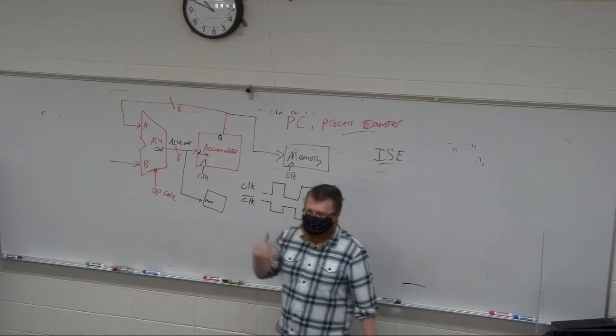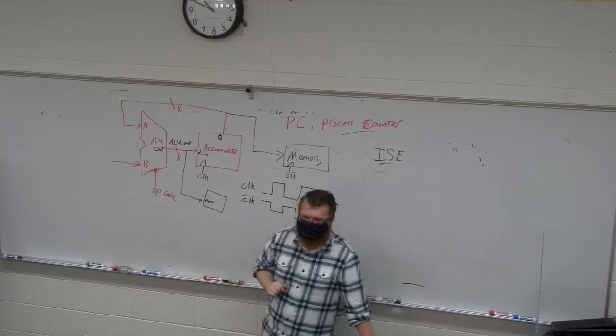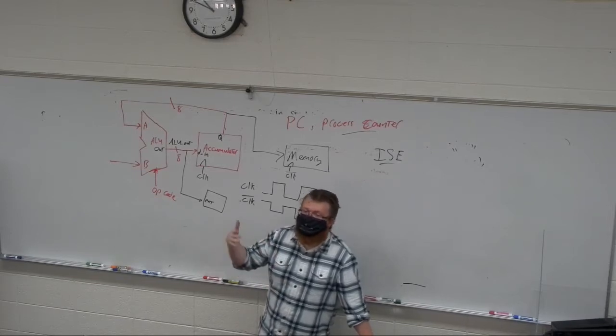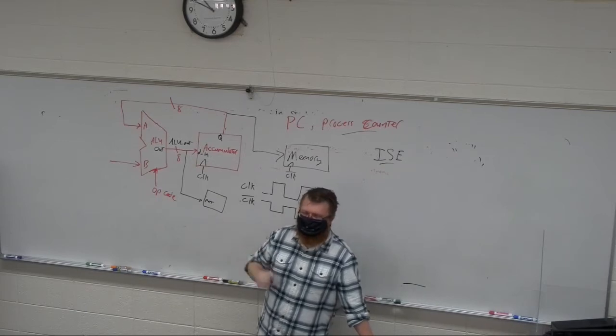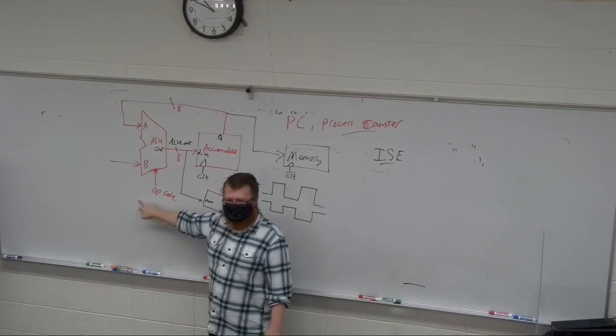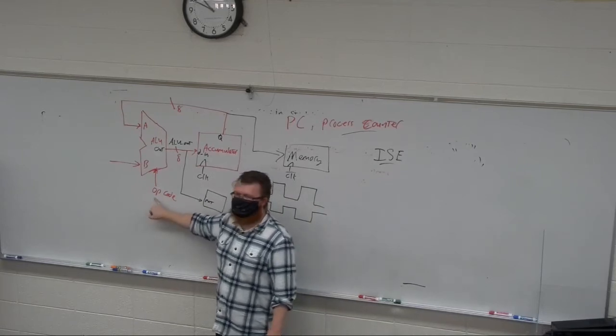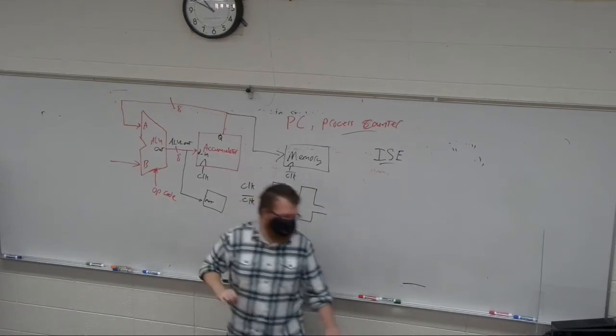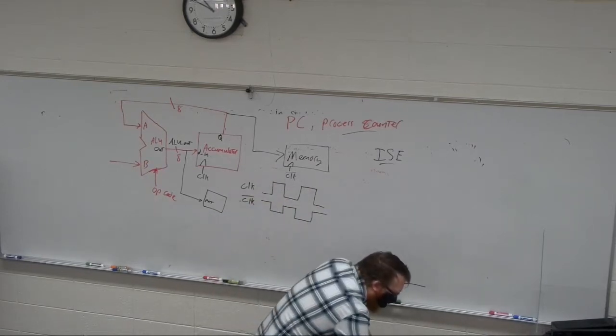So what we're really building up is essentially a small slice of a microprocessor. It's going to have more commands, and these commands are going to have to translate into opcodes, right? So your 8 bits of a command isn't just going to be an opcode. It's going to have more than that.